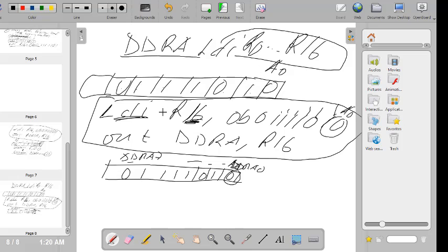The load immediate command is an assembly instruction that allows us, in AVR Studio, to load a constant into the register, and finally into its data direction register, the port, or into the port register, to give both the status and the direction of a port.